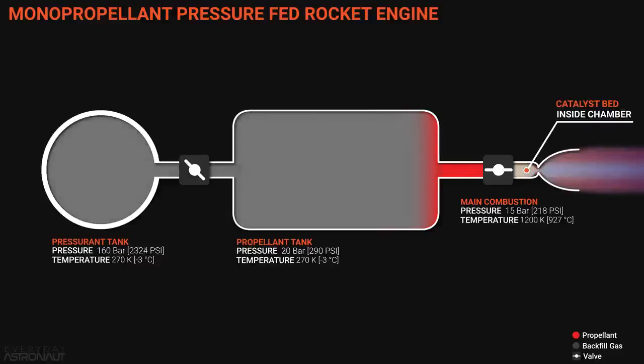Now, a lot of thought also goes into just how big to make the throat of a nozzle, as the size of the throat basically lets us know how much pressure will build up inside the combustion chamber. So if the throat is too small, there actually is a risk of pressure going back up the system. And of course, that is bad.